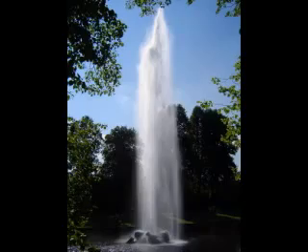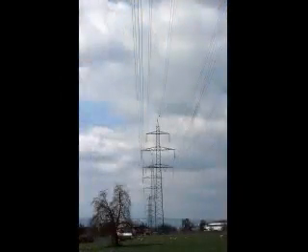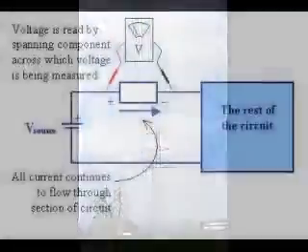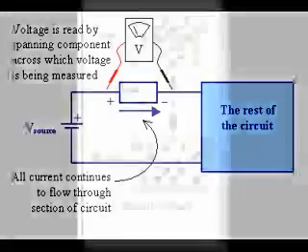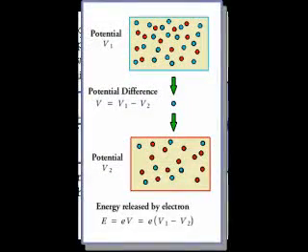The force motivating electrons to flow in a circuit is called voltage. Voltage can be thought of as the pressure that pushes electrons through the conductors. Voltage is also a specific measure of potential energy that is always relative between 2 points. When we speak of a certain amount of voltage being present in a circuit, we are referring to the measurement of how much potential energy exists to move electrons from one particular point in that circuit to another particular point. This potential energy is caused by a difference in charge. Without reference to two particular points, the term voltage has no meaning.